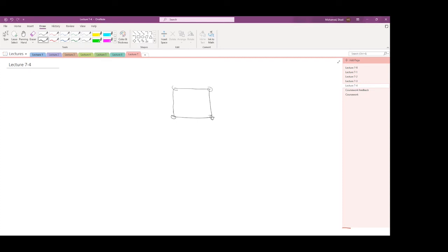So this is the linear element you have with the nodes. You can refine this one step into quadratic, and then instead of 4 nodes, you have 9 nodes. Or you can refine it even further. So this is linear, so the polynomial order 1.